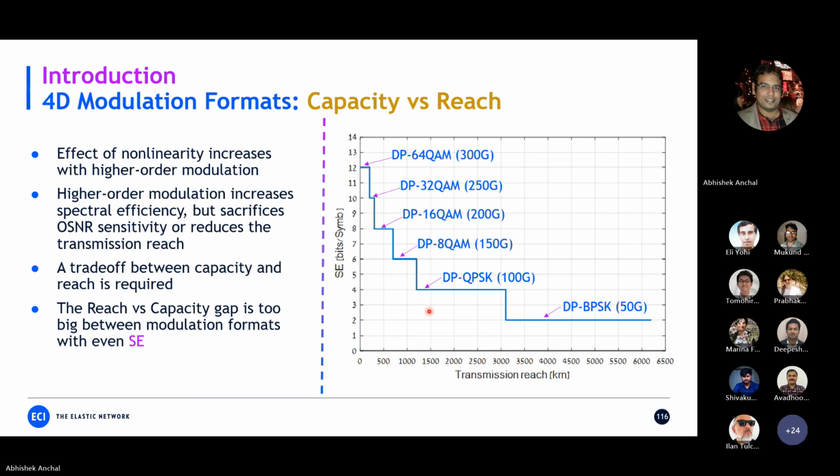So for example, if you're designing a network, you always have an issue with OSNR, because of bad fiber, because of some noises, some attenuation, etc. So the network is OSNR limited. So if you're designing a certain fiber link for, for example, more than 3,000 kilometers, the best option is to choose BPSK because the required OSNR of a BPSK transceiver is very low. So in a longer link, you can actually implement BPSK. But if you come back to lower distances and you want to increase the capacity, you can use QPSK because the required OSNR is a little bit higher, and at a shorter distance it can achieve that OSNR, and so on. So there is always a trade-off between capacity or spectral efficiency versus required OSNR or transmission distance.